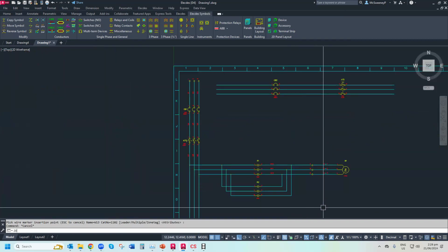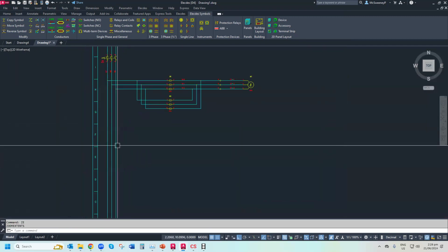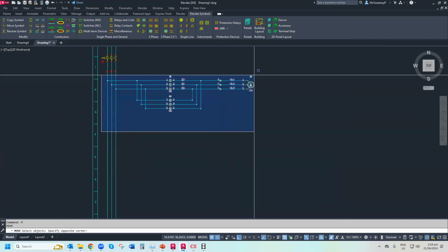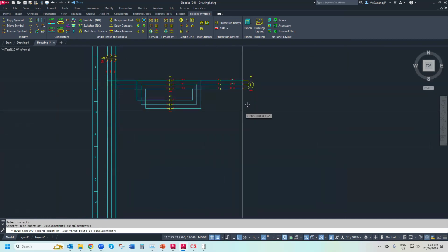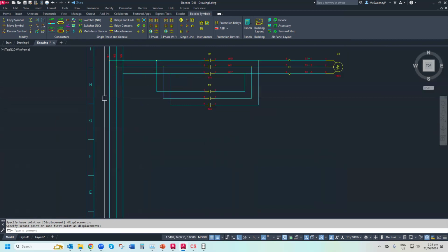Now, again, ZE. Escape. ZE. I might want to copy that circuit. Now, you showed me, Chad. I actually didn't know that. I use it from this way. In fact, again, I'll just use an M for move, using a few little AutoCAD commands or CAD commands. Sorry, I don't mean to say the opposition's name there. But there's my little circuit.